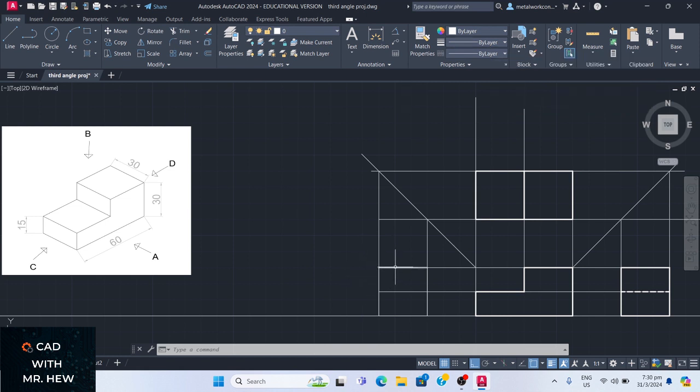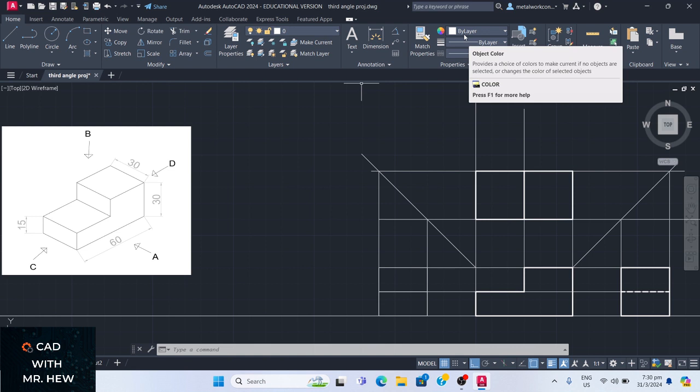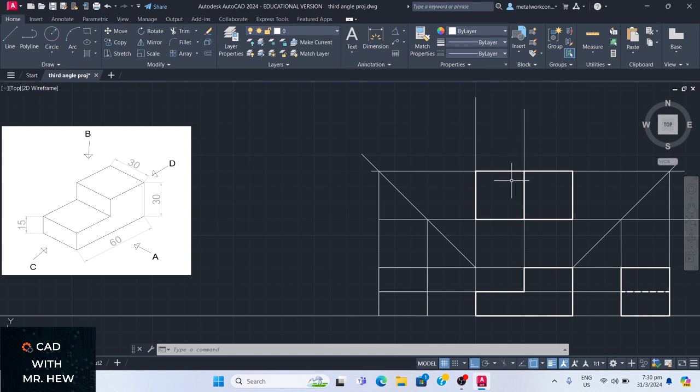So I'm gonna select the, well, I need another line here. So we're going line from here to there. Enter. All right. I want to maintain my construction lines to show how I got the objects for the front elevation, plan and the two end views. Okay. So that is why they are there. And at the end I'm going to turn them off and show you the relevance of drawing the lines for the different views by themselves, and I'm going to show that in a little while.